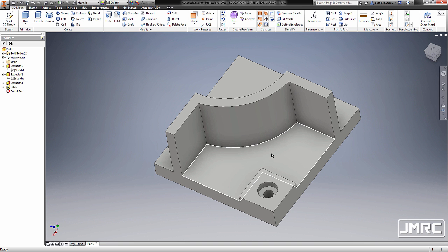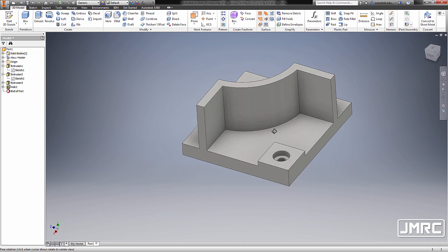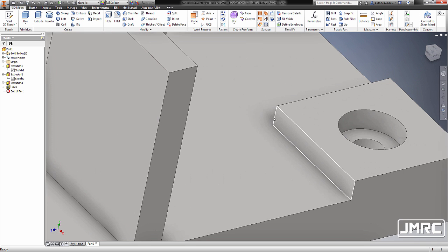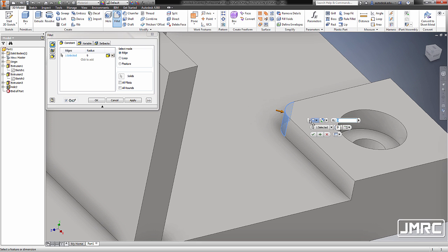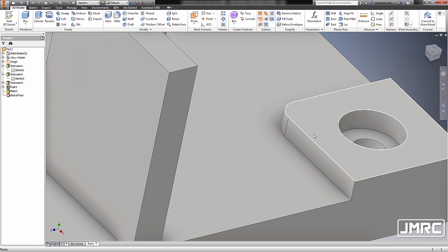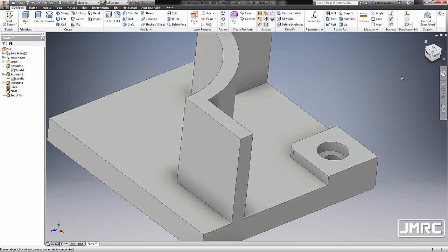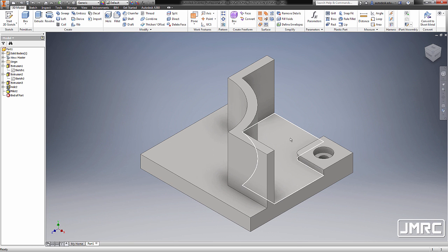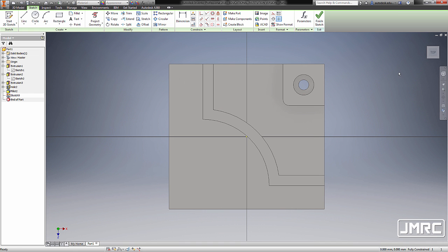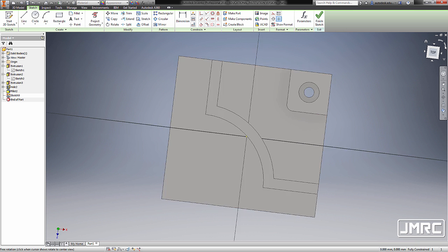But first, I'm gonna add a fillet on this edge. So selecting this one, left click, and selecting fillet. Now the value for this one is 9, keying in 9 and hitting the green check mark. Going back to home view, selecting this face and selecting create sketch. Going to our view cube and selecting this curved arrow pointing down.